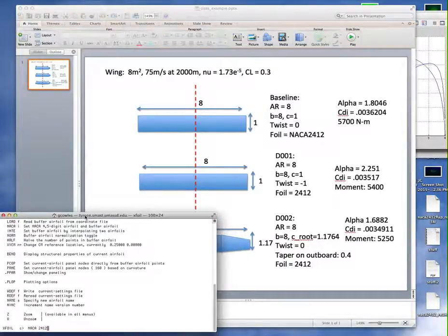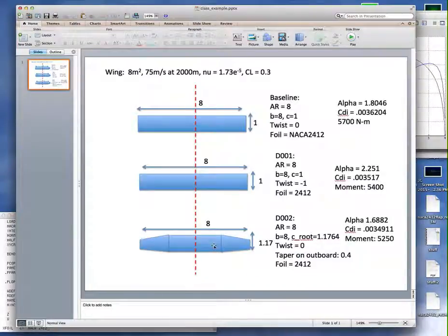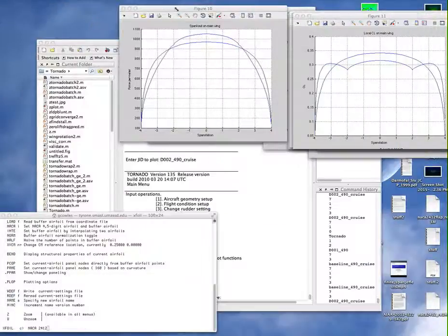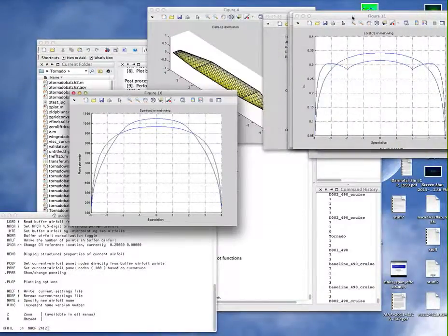And what we're going to do is base it on the profile drag experienced by a wing section running at the Reynolds number that's representative of the mean chord, which I have to compute for this, and at the lift coefficient of the entire airplane wing.